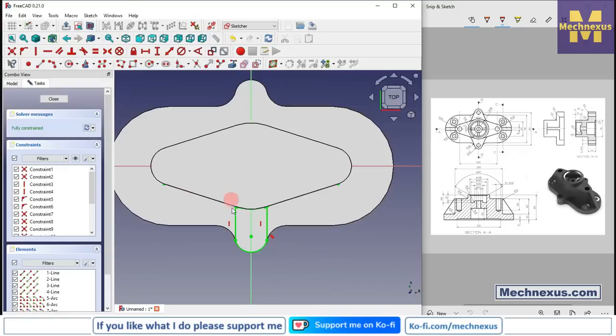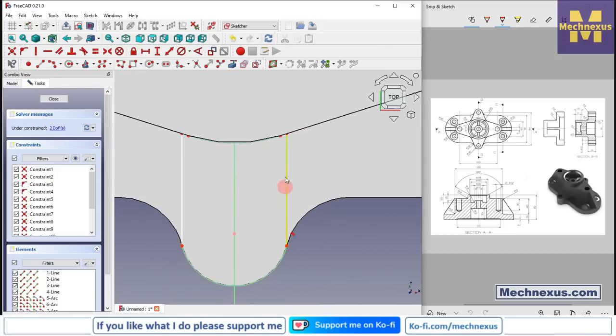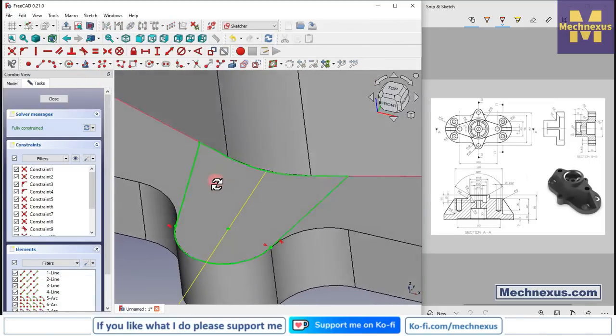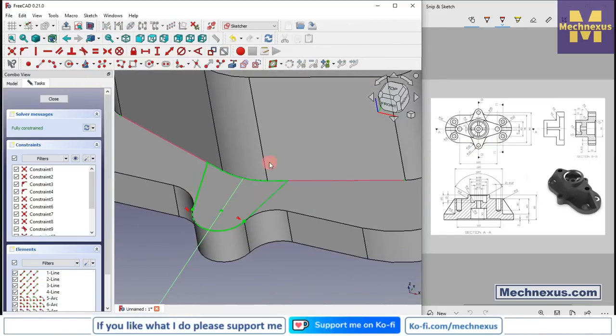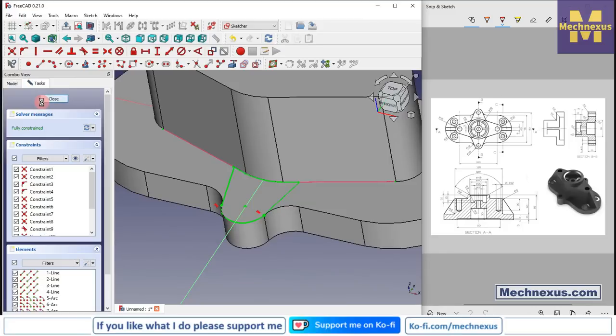So we will go to our sketch and we will delete these two lines, or we will press Ctrl Z, and we will remove this vertical constraint, and here we will use this and add a tangency, and select this and add a tangency. So this is how this profile is, and the best thing is that once we give the tangency here, this line automatically got extended. Click on close